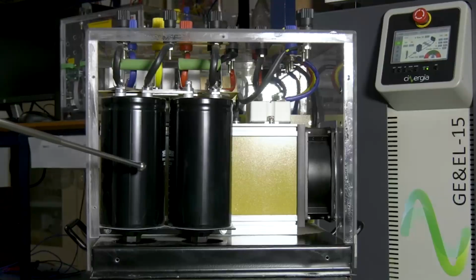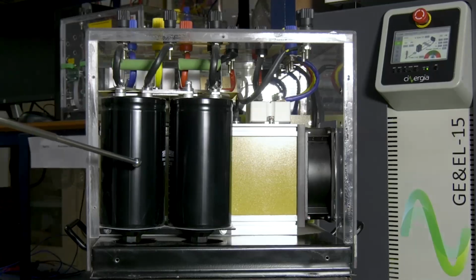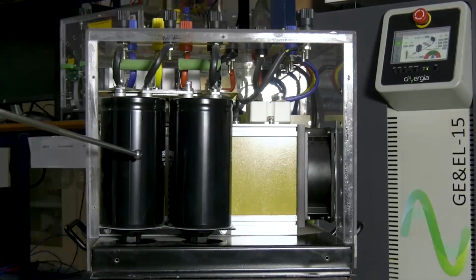One important thing to be noticed here is that the DC input capacitor or the DC bus should be rated to more than the peak of the grid voltage such that the power can be transferred from the DC side to the AC side. The basic understanding here is that until you create a voltage difference, it is not possible to transfer a reasonable amount of power from one point to the other.